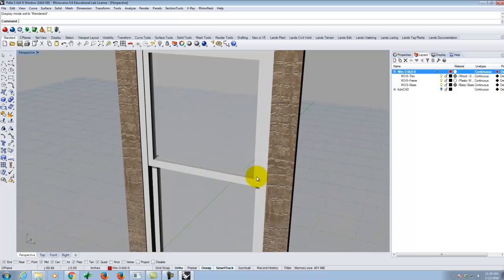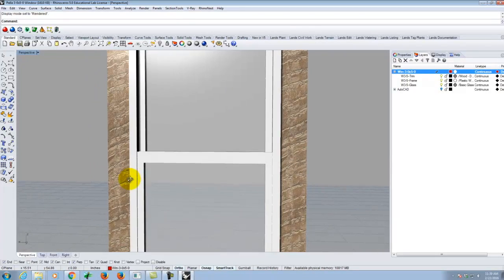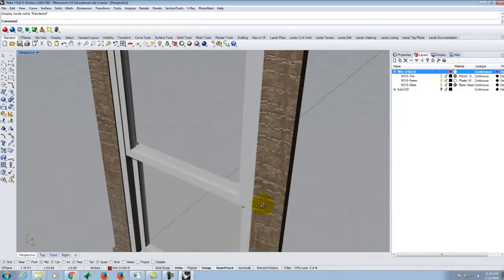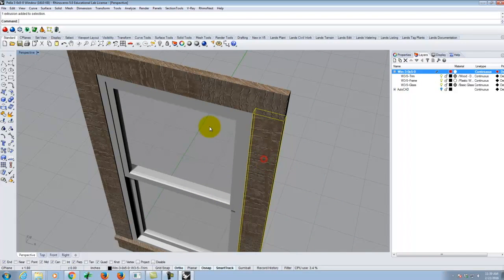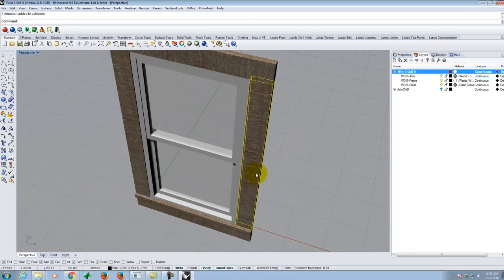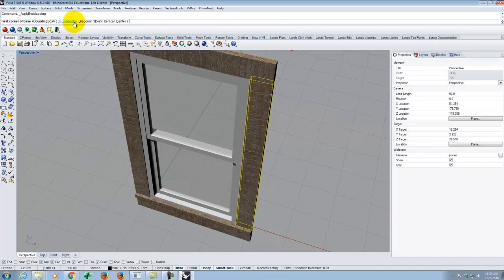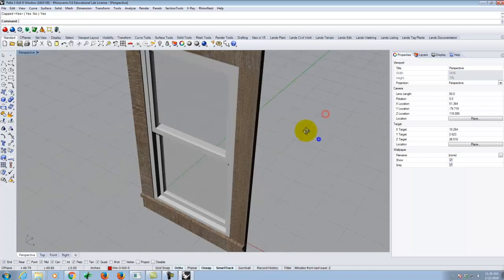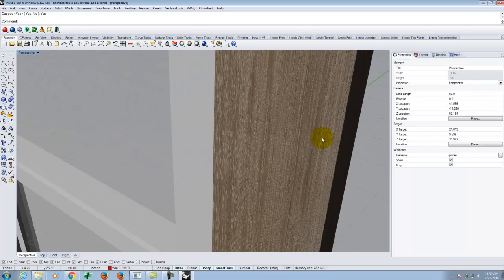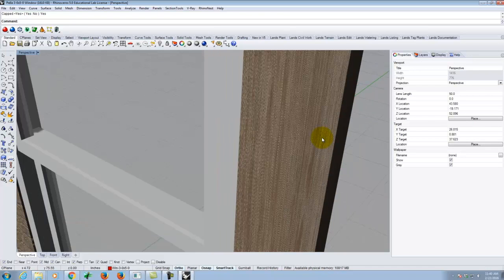I'm not so worried about the plastic that I made for the white window. That kind of doesn't make any difference. But I am concerned about the trim. So let's take each of these, and I'm going to have to work with them individually because the grain's going to run different directions. So let's take this first, and I'll go to my properties. I'll go to my texture mapping. This looks like a box, so that would be a good place to start. And we'll do a bounding box, world, capped, and just by doing that, it's going relatively in the right direction. Okay, much better than it was.